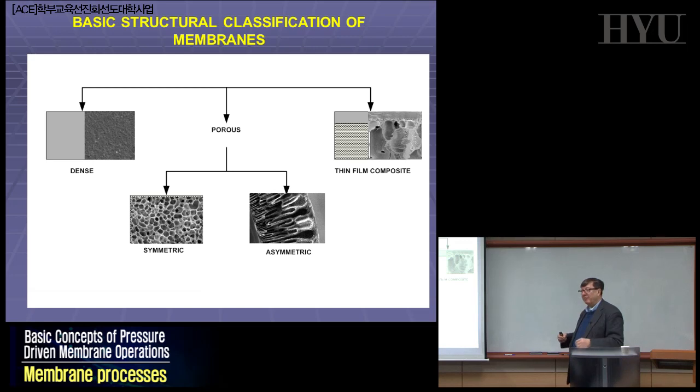You'll be able to have what we call fast, immediate demixing or slow demixing, and by changing the velocity of phase inversion, you can realize an asymmetric structure as this one or this one. Also here you see very large pores, and these here are much narrower pores. So this is one material where, during phase inversion, you can realize this asymmetric structure.